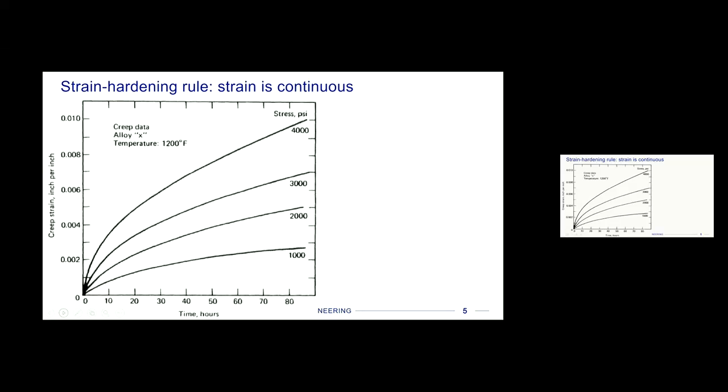And so it's much easier to add up the strains because we just go up the y-axis and that's our total creep strain, okay? And so if we go back and think about the levels that we had: 1,000 psi for 10 hours, and then 2,000, 3,000, 4,000 for 20 hours, and 10 hours. That's our mission cycle here. The first amount of creep strain that we get is exactly the same, right? So we have 1,000 psi, we go out to 10 hours.